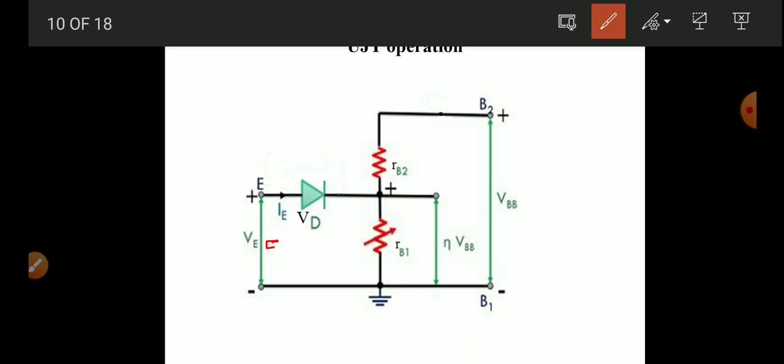When the UJT reaches the peak point voltage, the diode becomes on, and the P region is heavily doped. There, more holes are seen in the P region. So when the diode becomes on, the holes move from higher concentration to lower concentration. In the N region, holes are in low concentration, so holes move from the P region to the N region.